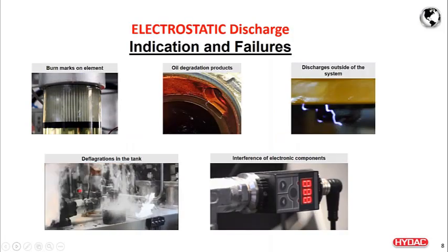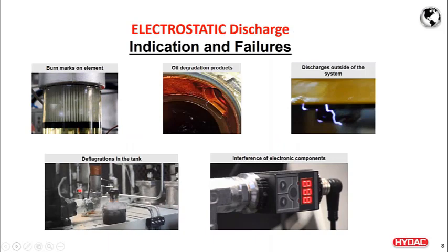So here in this slide, what we are showing is the different indications. The first one is the burn mark that we talked about. When you have the filter element generating a lot of charge and discharging within the filter element, that is going to cause burn marks in it, causing a lot of holes and not increasing the delta P throughout the service life.